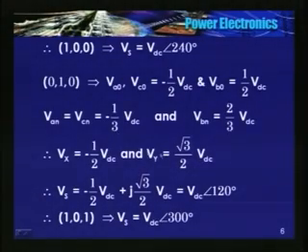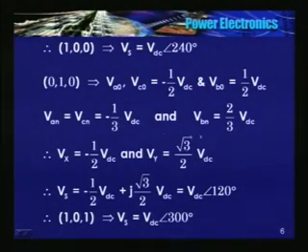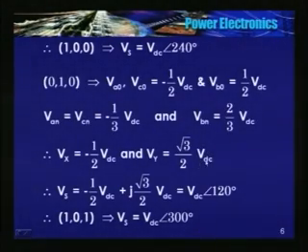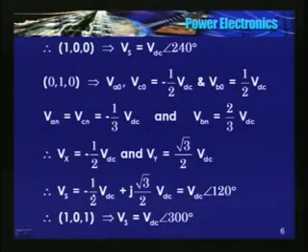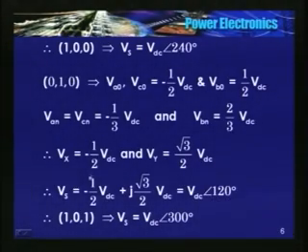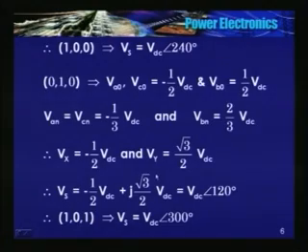Okay, I will substitute for VIN, VCN and VBN. So it is again root 3 times VDC. Therefore the space vector is minus half VDC plus j root 3 by 2 times VDC. So again minus half plus j root 3 by 2, magnitude is 1, but then the angle is 120 degrees, cos 120 is minus half, sin 120 is root 3 by 2.